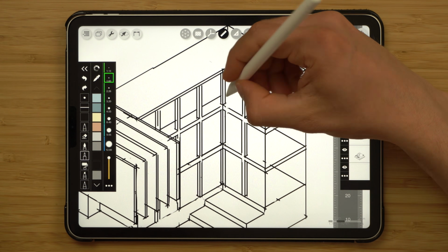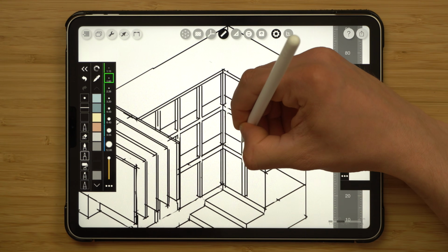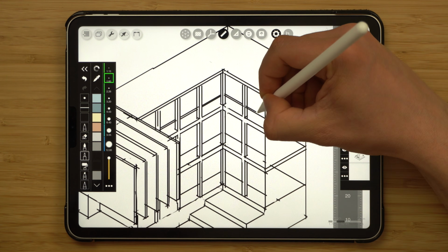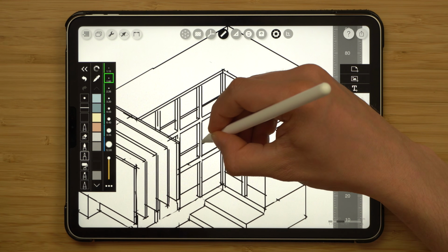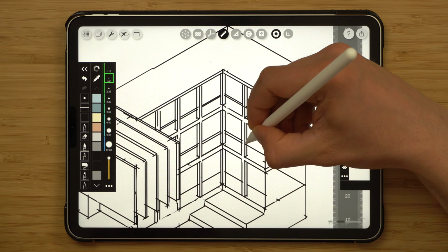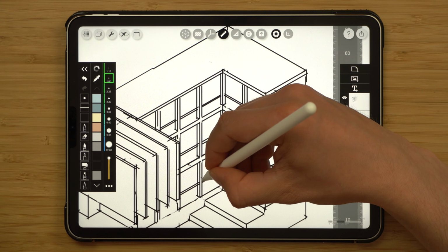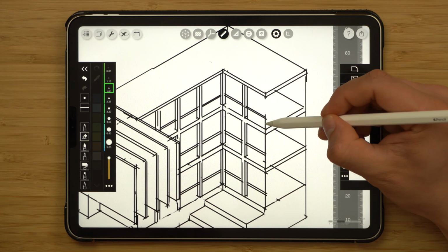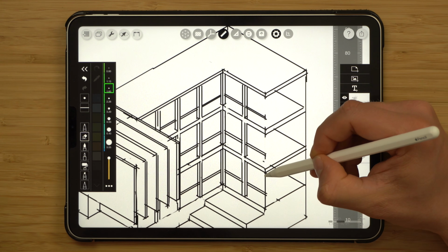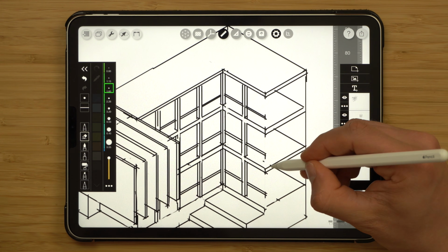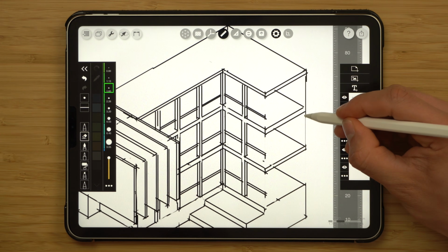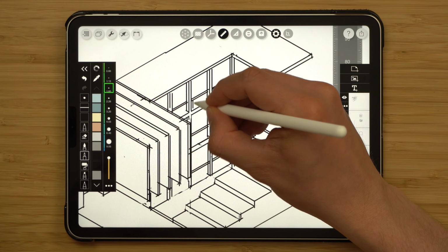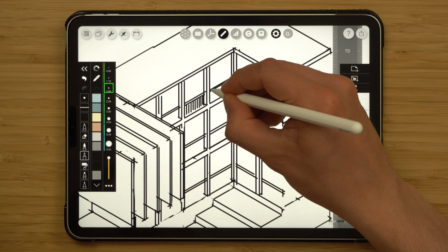Lastly, I'll just add a couple of railings with the corresponding thickness. It's much easier to start adding these details once the base structure is done. I usually like to, as you can see here, do them all at the same time. That way I don't miss a thing. So if there are multiple objects to pull in the same direction, I'll do that at the same time, as well as erasing bits, like you can see here. And then let's add subdivisions for these railings too.